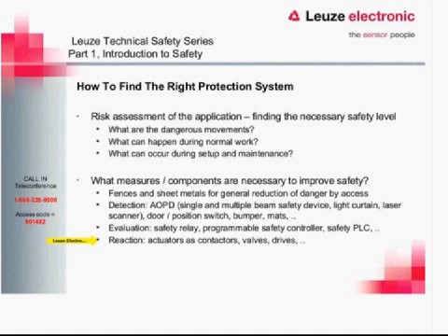It's not always complete when you put a full safety system onto a machine. That doesn't necessarily always fix the problem. You need to look at how these valves are going to be affected by taking power away from them, basically. So if you have a machine that's got single solenoid valves on it, you remove power, that doesn't necessarily stop motion, that just reverses motion. So a lot of these things need to be taken into account when you're doing a full survey of a machine.